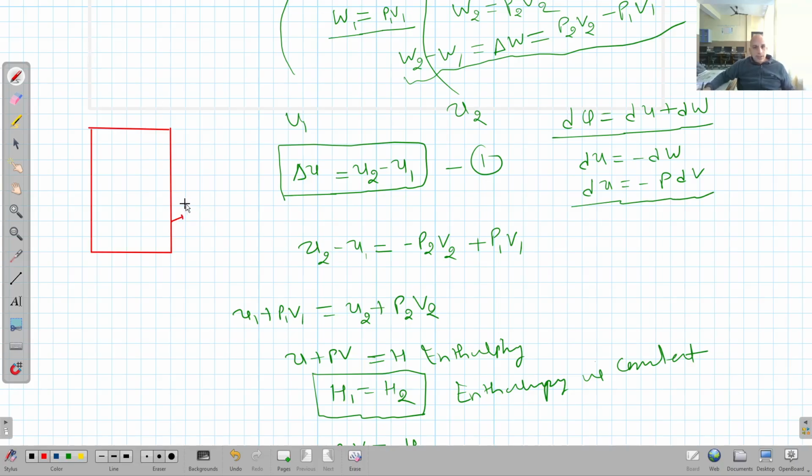And we are using some gas that is stored inside this compressor unit. This compressor is compressing that gas up to a very high pressure. Then that gas is allowed to expand through the throttles. You might have seen on the back side of the refrigerator, there is a mesh of fine wires or fine tubes, right? So when that gas is allowed to pass through all this setup, the gas is throttled, its temperature is reduced, and then finally it is circulated inside the refrigerator.